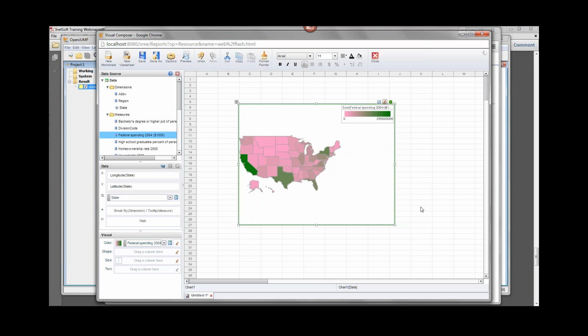Now you can do maps that even go beyond actual geography. If you had a shapefile of, let's say, a warehouse floor plan, you could load that shapefile in OpenJump and run through the same set of steps. It would be just a set of polygons, just like this is, except that it would be the floor plan of a warehouse, and you would do consolidation and reducing precision and reducing points on the boundaries, all the steps that we ran through, and export it.